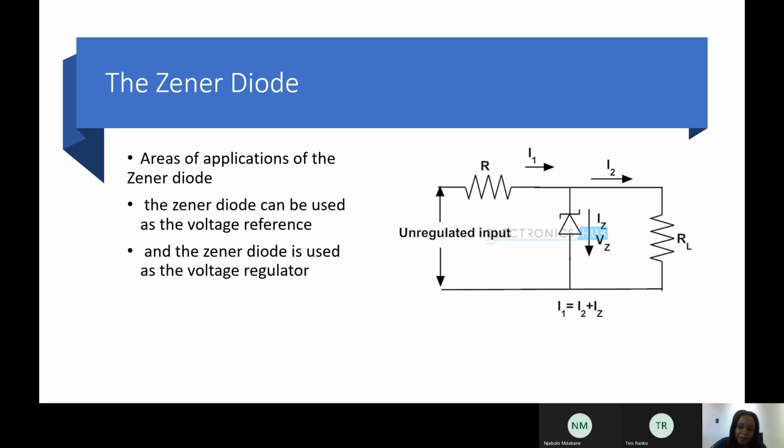It's used in the power supply at the last step, which you didn't really cover. It's used there because when power comes out of the second filter, it is filtered out and the signal is a little bit better. It becomes more like a DC, but we still have that bump. That bump is something we don't want. We want it to be straight.